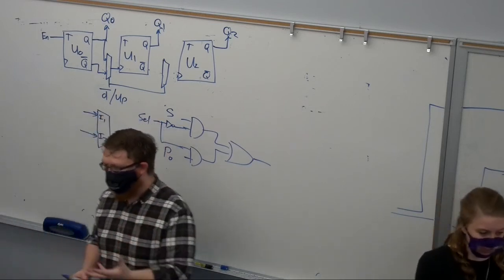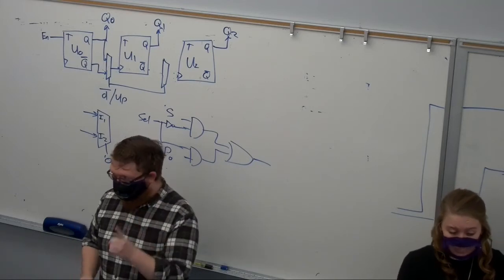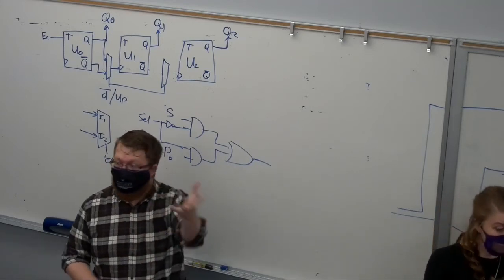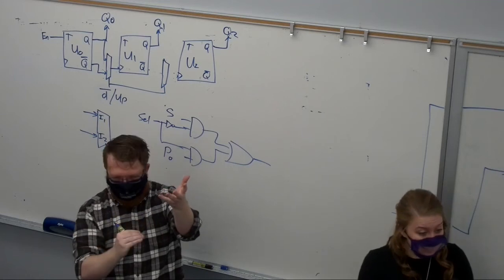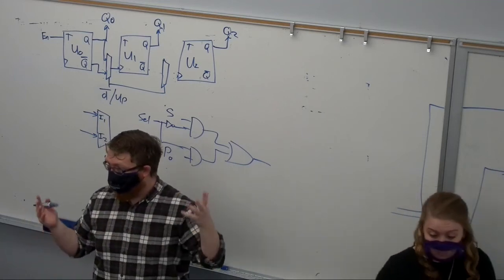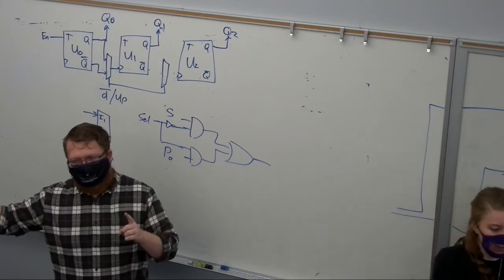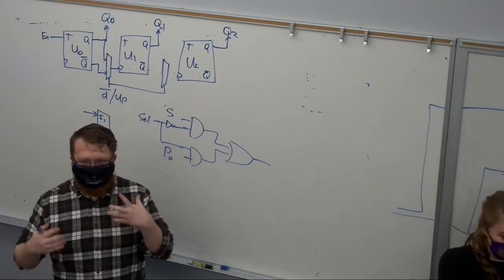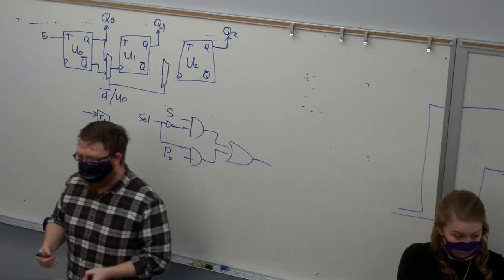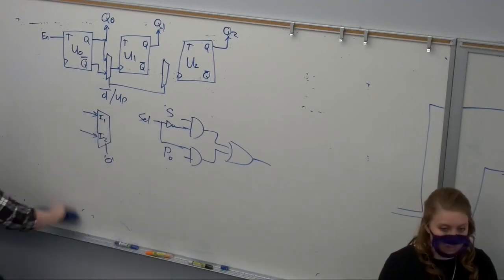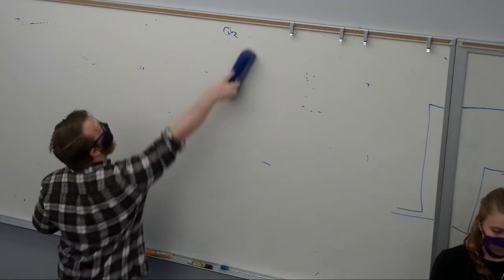Well, we could build a shift register, and we will in class, that is n bits. So I would write code one time, and then when I declare that component, it's an n-bit component. But then when I create the instance, I could make one 8-bit, one 4-bit, one 3-bit, however many I want, without writing new VHDL code. The same thing applies for adders. I could build one n-bit adder, write code one time, and on the instantiation I can choose how many bits the adder is. This is a little confusing sounding right now, but fortunately, generics are really easy to use.